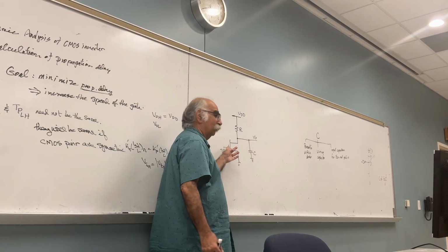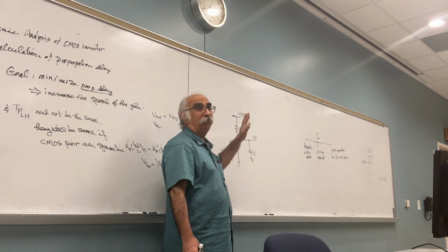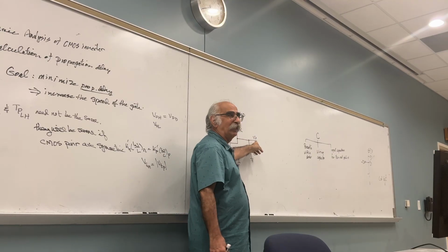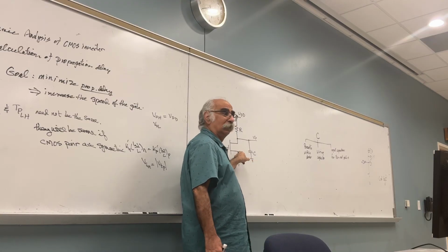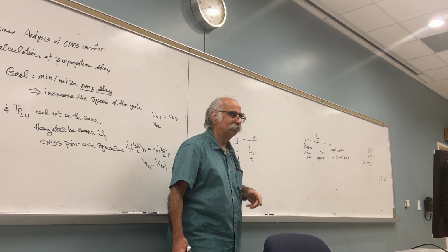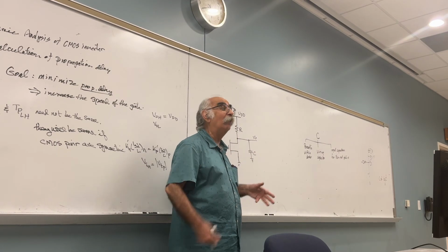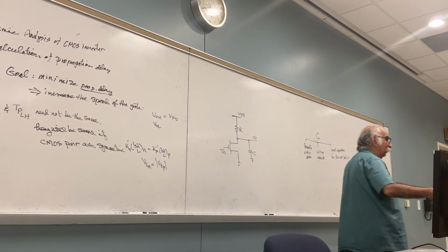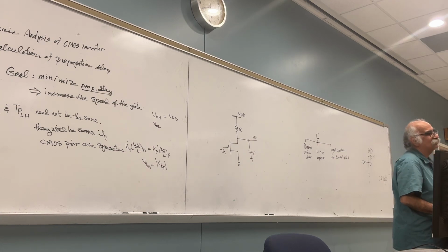Let's assume that the input was high for a long period of time. What happened to the capacitor? The capacitor discharged through the NMOS to what value? Not zero, to VOL. It cannot reach zero, because VOL is a minimum. Did you follow me or not?